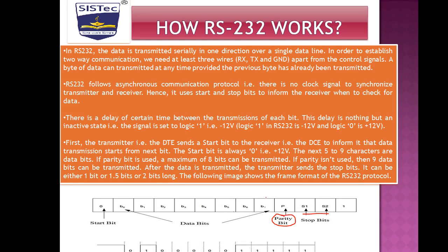These are our data bits, and the first bit of this data frame is the start bit, which is represented by 0. In this example we use 0 as the start bit, then the data, and we use 2 stop bits, 1 and 1, and 1 parity bit, 1.